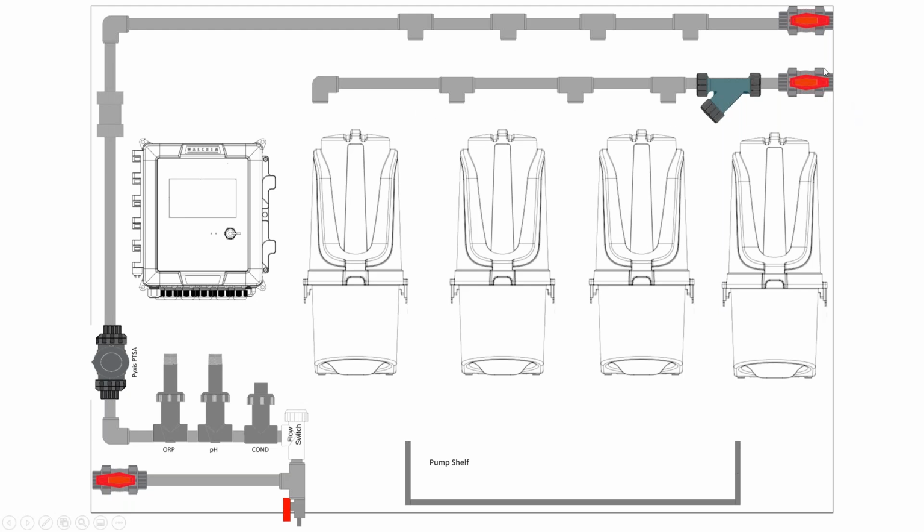Now, some folks like to use the tower water to feed the water into the UltraM, your choice. We like to use the city water. The reason we like to use the city water is there's less chance of the biofouling and the other incidents that are occurring in your cooling tower coming into your UltraM's feed system.